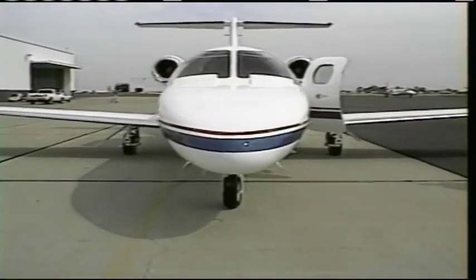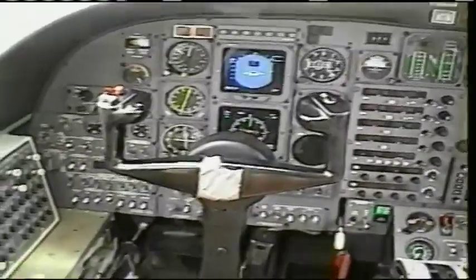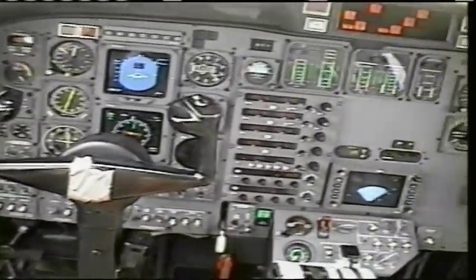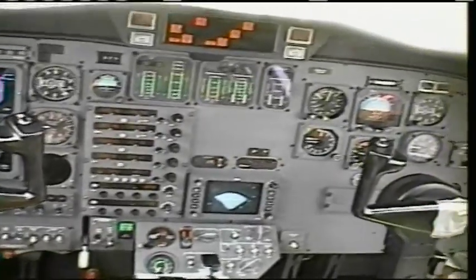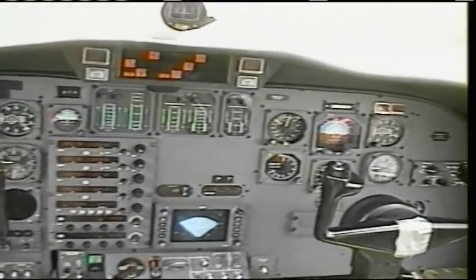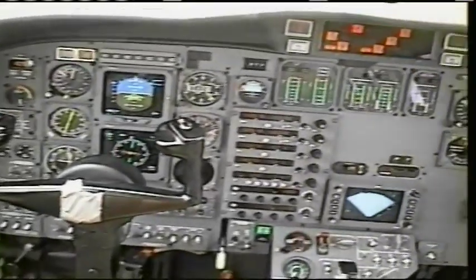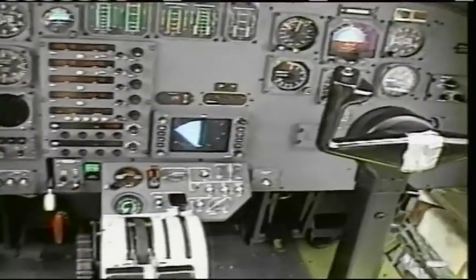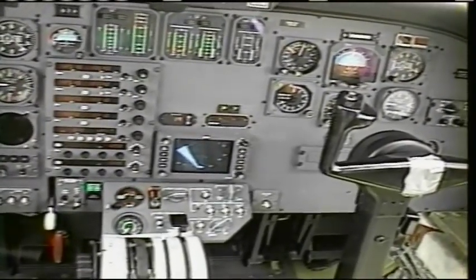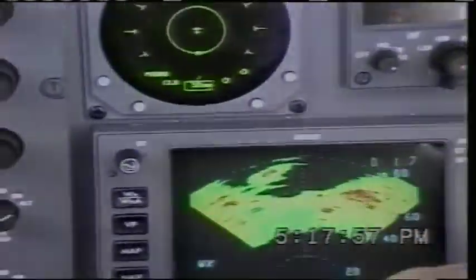As a general comment, it should be noted that the most important radar skill a pilot can possess is the ability to use the ground echoes as a reference point for proper tilt management. By learning to use the beam to observe the ground in good weather as often as possible, you will become familiar with its reflection characteristics. Having gained this familiarity, you'll be able to properly adjust the tilt angle of the antenna to make valid assessments of the weather conditions. Remember, weather radar is a vision extending tool for pilots that provides significant warning of hazardous weather. Use this tool wisely, and it will add to the safety of your flight.